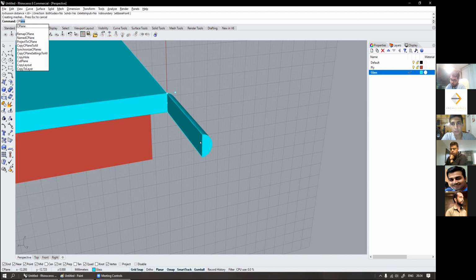As far as I know, there are two areas where you would need this to be a solid thing. One is when you want to create a construction drawing. Second is when you want to use it for, let's say, 3D printing. Once you transfer this Rhino geometry into any 3D software, it will automatically know that it has to be a solid, and will treat it like that.